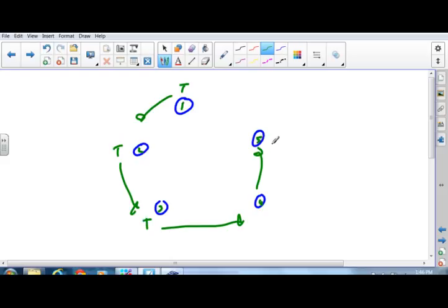And now number 5 would have the token, and he would transmit to number 1 saying, I got it. And that's what a Johnson counter would do. The person that is going to be enabled is the guy that has a 1 and a 0 by his name as you move the Johnson counter by, and now you know whose turn it is.